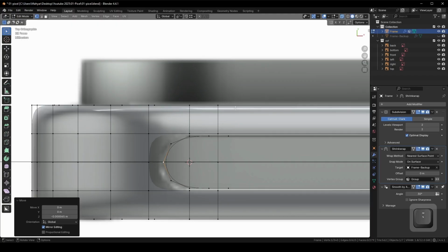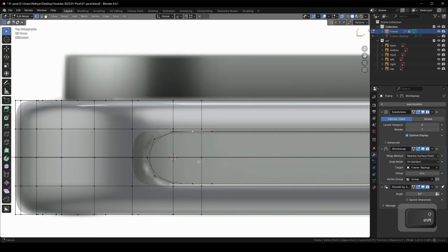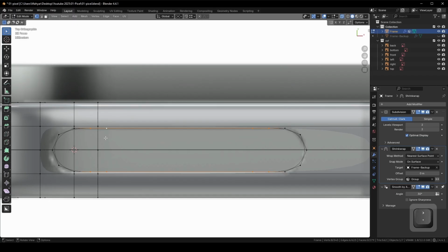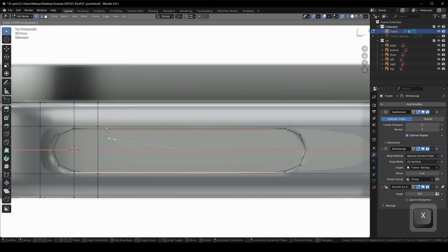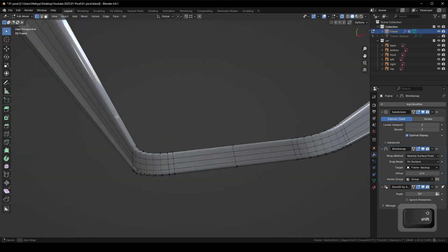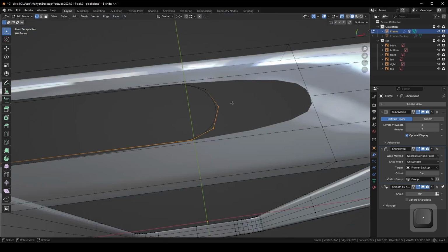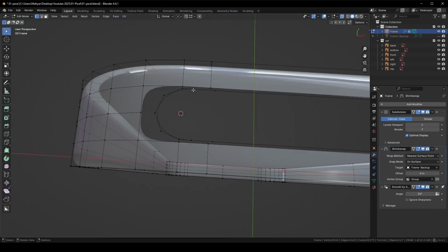I'll go to the top view. I think we can select these vertices in the bounding box center, S X to make them closer, move them closer to the circular shape. Now we can connect them. Select, press dot to focus on the view. The edge flow here is not good enough.